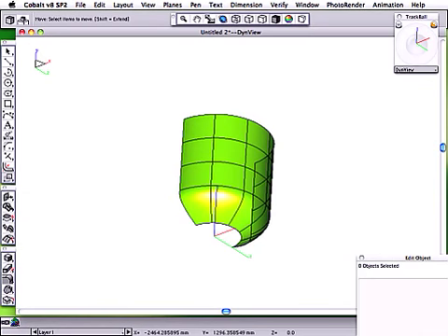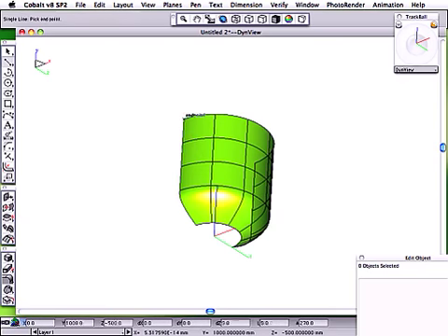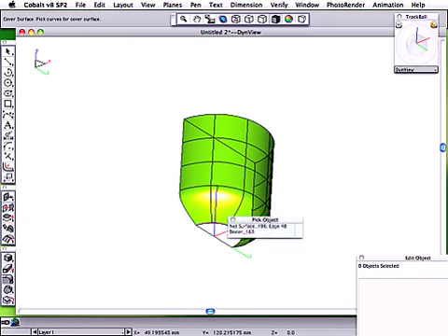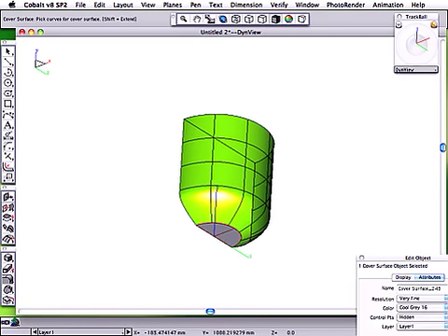Now, to turn that thing into a solid, I can either thicken it or I can fill in the remaining surfaces. So put a line to join there and another line to join there. Now I can put the caps on this thing. So I'm going to do the bottom first, pick the edge or the spline, and another straight line. Same again on the top,